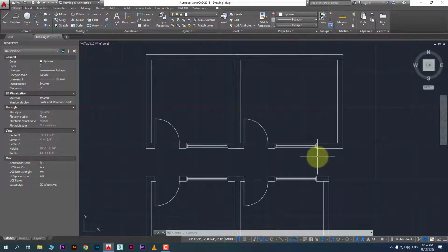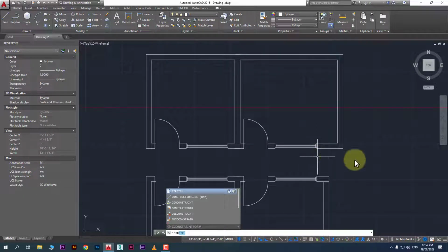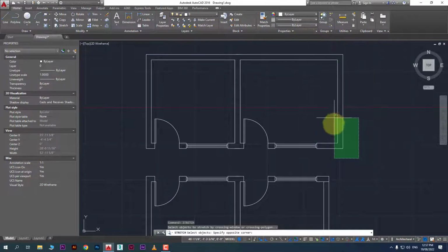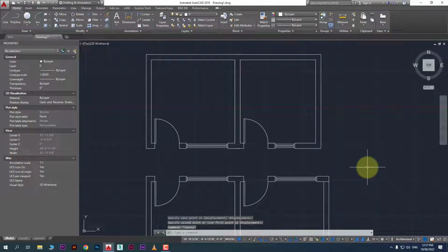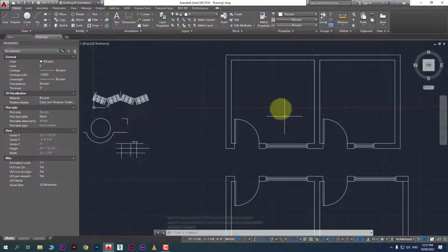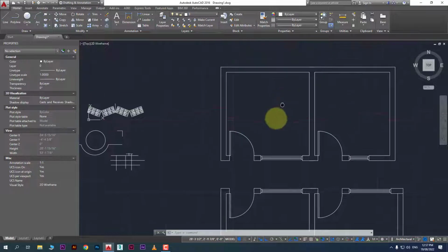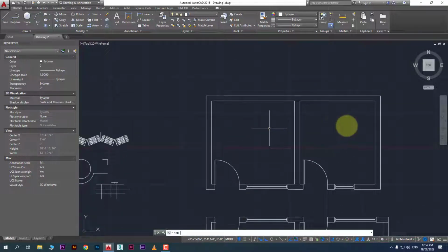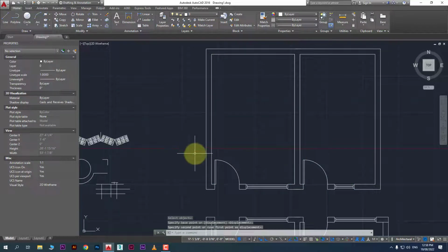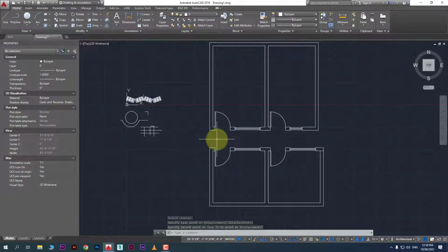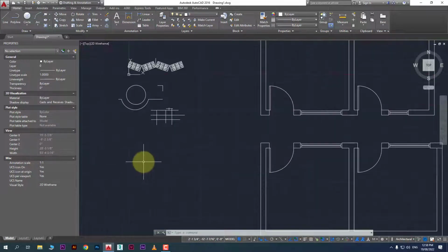Also you can make shorter str, alright, and only the direction you have to define like this, okay. I want to shrink window also, so just make like this, so you can make also like this manually. So stretch command is also very useful. No need to change your whole design, you can stretch from wherever you want, like str, I want to stretch from the upper side, just you need like this and you can stretch, and you can give a specific distance as well, okay.